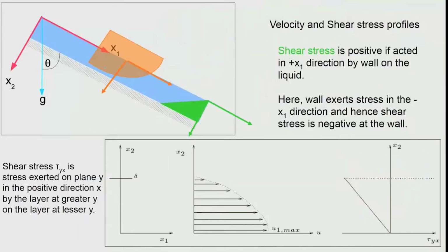So, when we plot, it looks like this. The parabola has a shifted edge. So, this is how the velocity profile should look, and here I have drawn the parabola in a flipped direction intentionally to show you the nature of the parabola, and you can see only half of the parabola is actually applicable, and the slope here is 0 when you look at here in this direction. So, ∂u/∂x2 is 0, okay,